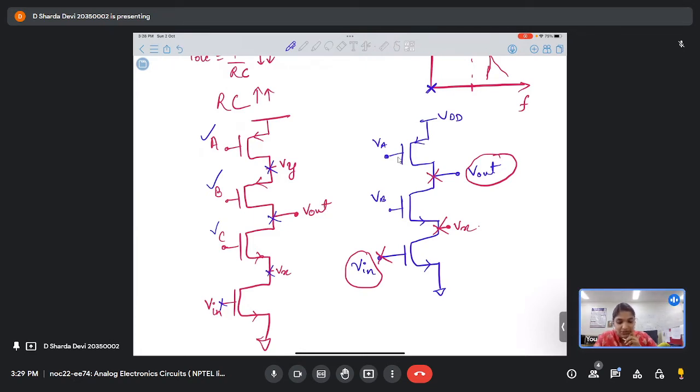First of all, the potentials at A, B, C will come from some sort of resistor divider circuit, and these voltages are basically used to bias your transistor. The most common method to bias your gate is using a resistor divider bias.